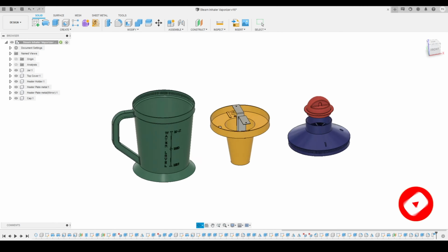So it's a very simple design I had created using Fusion 360, just by using one revolve tool and a sketch. Here you can see Sketch 1. Now I will revolve this bottom profile. I will activate the revolve tool and select this bottom profile, and then activate the axis and select this vertical axis as the axis.